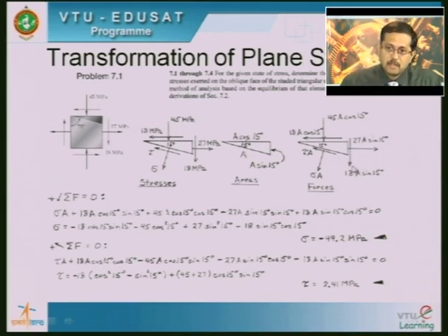Next, if I take this, I have to resolve this along this axis. So, when I resolve it, this sense would be same as this along this. So, it is going to be 18A sin 15 degrees into this is the angle that we are getting. So, it is into cos 15. Both the senses are same. So, we get this to be positive.